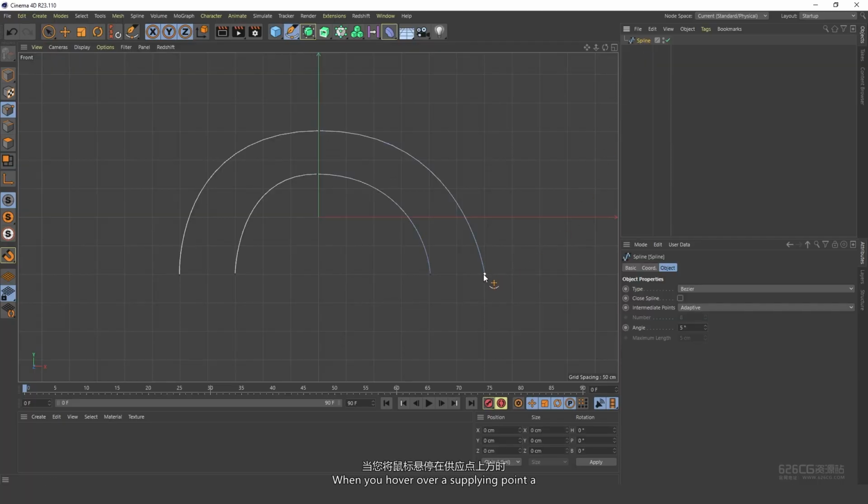When you hover over a spline point, a point transformation hint appears. By selecting it, the Bezier handles setting appears. If you right-click on the selected point, a menu with the following settings appears. Here we can delete, detach, change the interpolation of points.